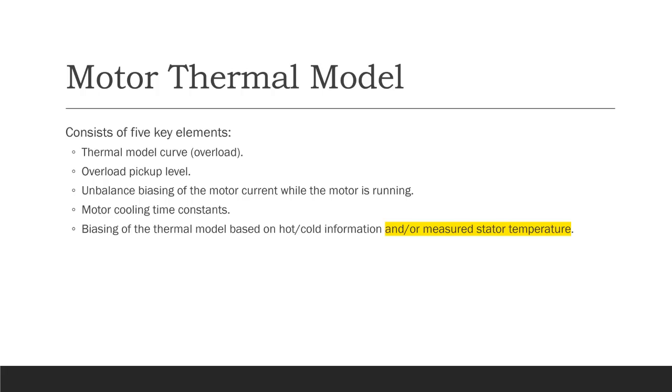And we will talk at a later date about things like biasing of the motor because of voltage unbalance, as well as playing around with the motor cooling time constants, and also biasing of the motor based on the hot-cold curves that we obtain from the motor manufacturer.